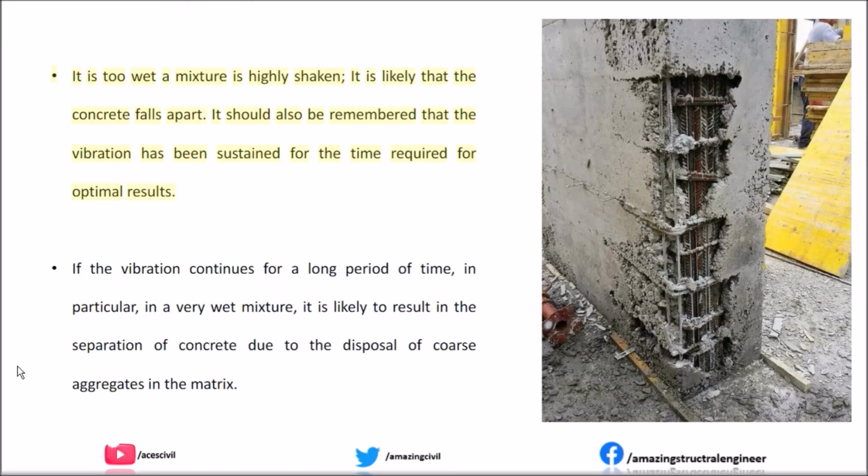It should also be remembered that the vibration should be sustained only for the time required for optimal results. If the vibration continues for a long period of time, particularly in a very wet mixture, it is likely to result in the segregation of concrete due to the settling of coarse aggregates in the matrix.